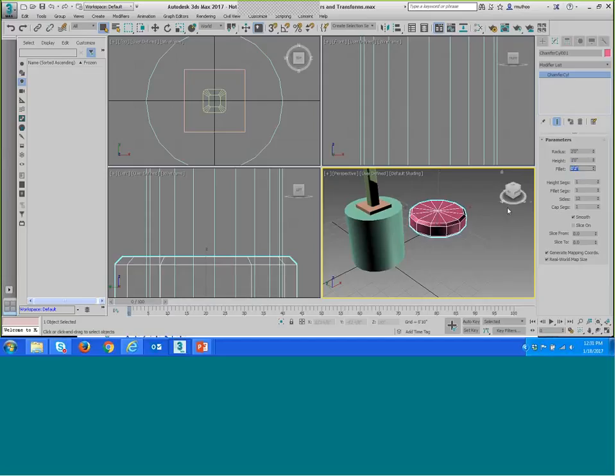So that's what happens with the fillet option. It gives it a beveled edge right here. And we leave the sides as 12. We can reduce it. We can increase the size right here. And that's for the housing for the lampshade. So maybe name it as housing right here.